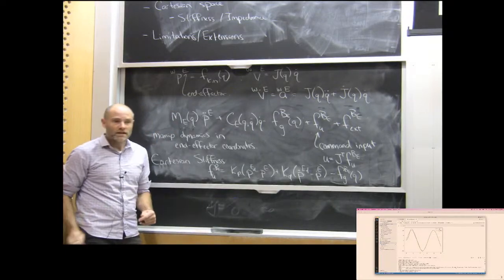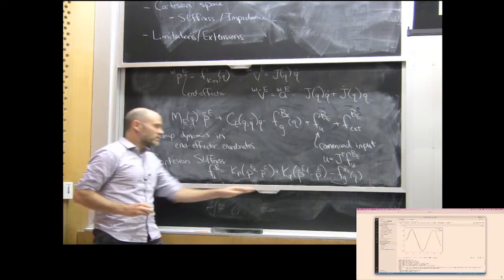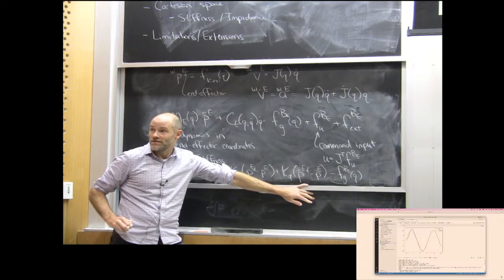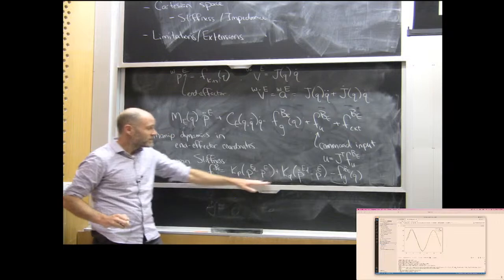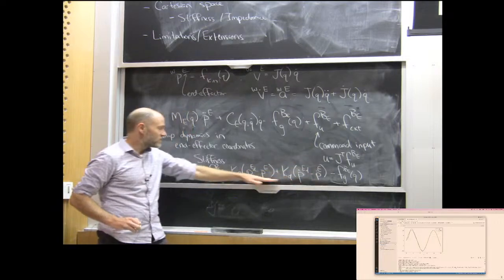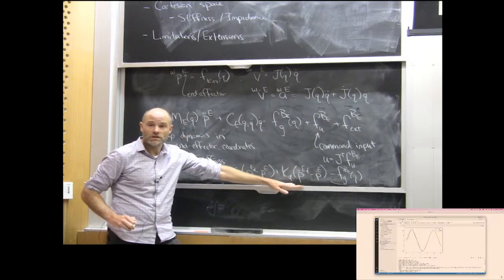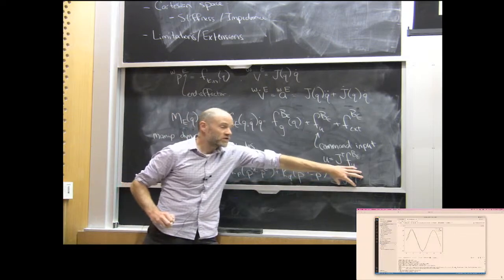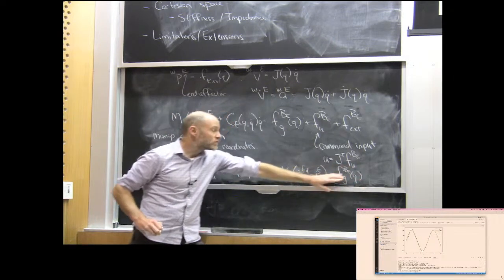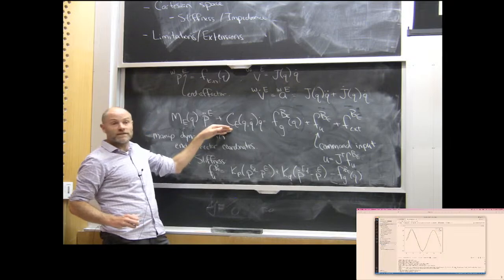Now you see why I was worried about snowing you with the details. But I hope you see by the simple analogies that this is really just writing the PD controller, canceling the gravity, but we're doing it in the coordinate system of the end effector dynamics.